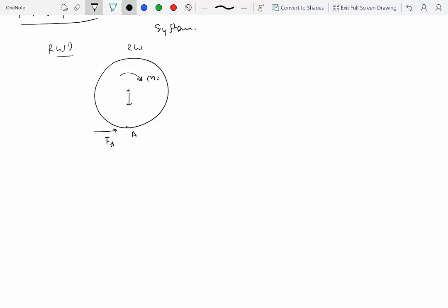You have the gravity, and you also have some vertical and horizontal direction forces transferred to the wheel through the axle, right? And this could be the weight of the car that is being applied at the center of the wheel, the vertical direction and the horizontal direction force as well. So these are the forces acting on the wheel and the normal reaction, right? So clearly NA is not going to do any work. We know that because the wheel is moving in the direction which is perpendicular to the normal reaction.